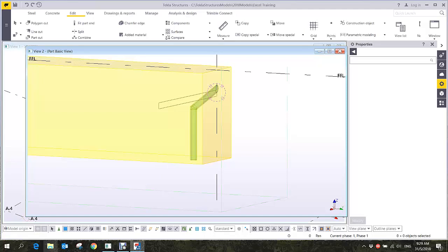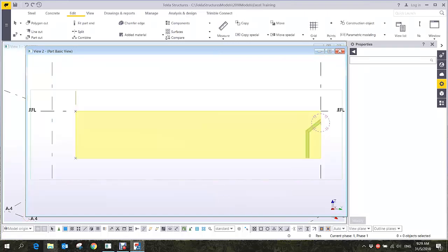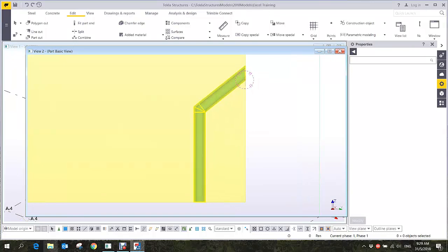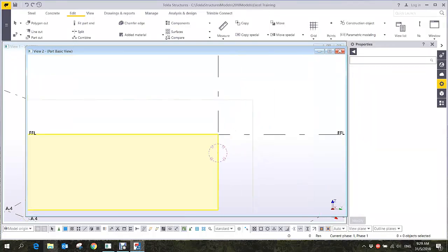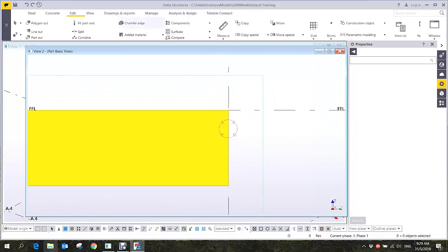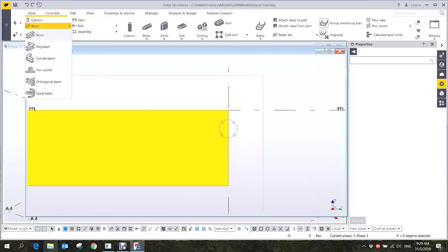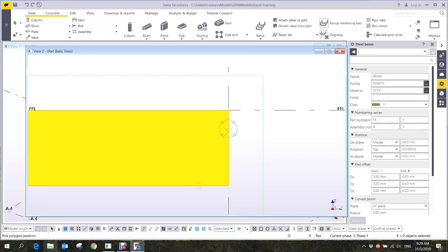Snap tools. And also, look, if I have a solid render view, I cannot pick. Not only ortho, look at this one. This one is a solid view, right? So look, if I click on this one, see, I cannot click here, right? Control 2, and then I can click. Control 2 makes it transparent.